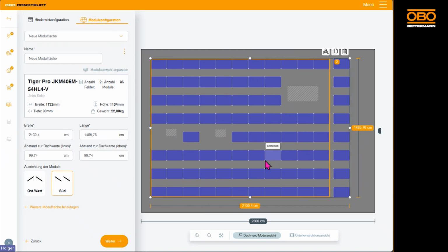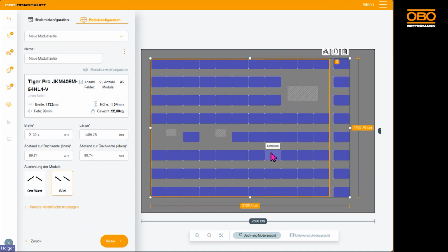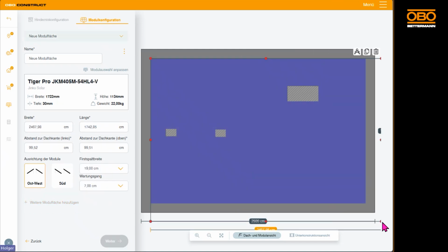clearly recognize that these orange circled rows or areas create distinct separations between the individual module fields displayed on the screen. Because here, a thermal separation is necessary, since the total length of this rail, which is built and used here, needs to be separated after approximately 20 meters, where a second segment then forms. And this, from a static perspective, will also need to be carefully considered individually in the later stages of the process. We'll soon observe how the small field compares to the large one.